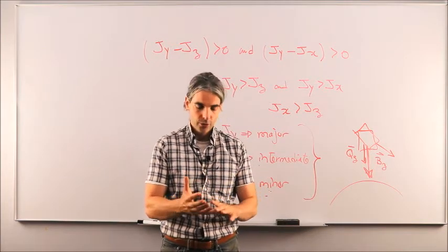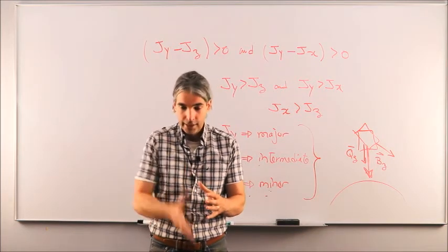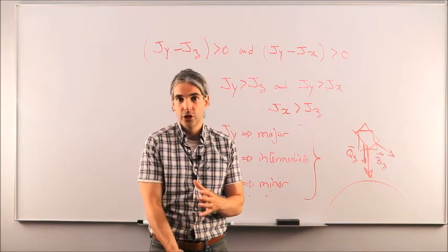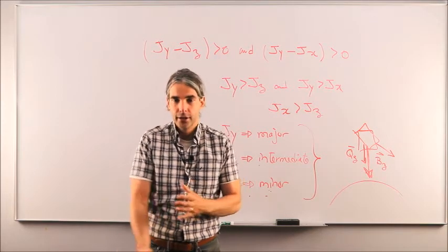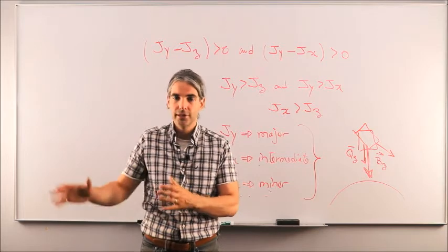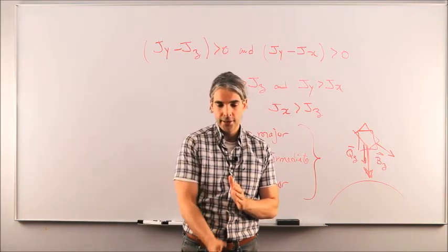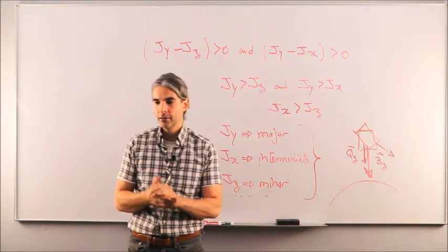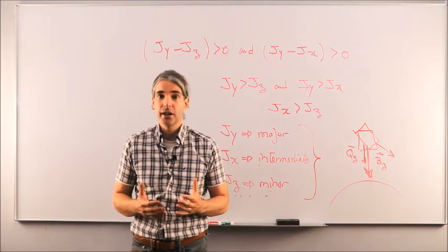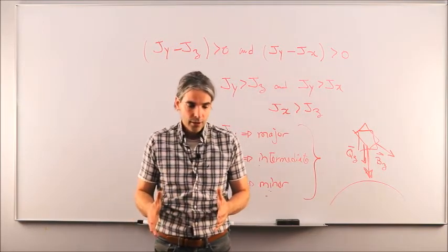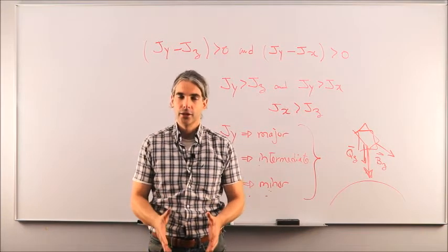Or in other words, the roll and pitch angles that define the orientation of the spacecraft with that nadir direction, or with the roll-pitch reference frame, same thing, will be bounded and will oscillate, but will not grow unstable. And here we're talking about a pointing accuracy in a nadir direction of about maybe 10, 12 degrees. So it is not super accurate. Still, it would maintain a rough orientation of your spacecraft, always pointing down at the ground.